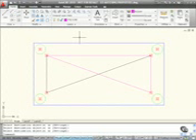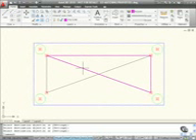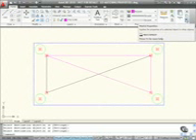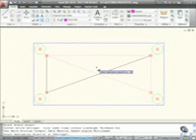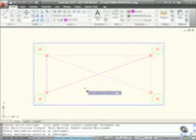Easy. The benefit of that is if you pick up somebody else's drawing and you've created an object on their drawing on layer 0, what you can do is you can select a similar object and match those properties across to the object that you've drawn on layer 0. So there's the polyline there. And again, what we're going to do is match properties now, like so. Come into the drawing area and select our source object, that one there, and then destination object, that one there. It changes, and enter to finish.